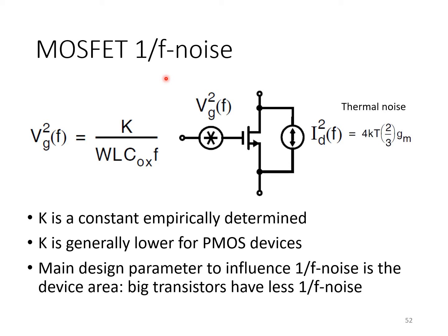And the frequency with which this occurs is governed by a certain stochastic law that ends up showing up as a noisy process with a power spectral density proportional to 1 over F.